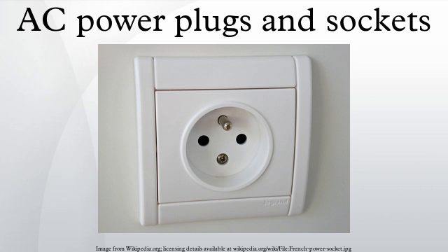Argentina: IRAM 2073 and 2071 and compatible types. The plug and socket used in Class A1 applications in Argentina is defined by IRAM. The applicable standards are IRAM 2073, 2-pole plugs with earthing contact for domestic and similar purposes, rated 10A and 20A, 250 VAC, and IRAM 2071, 2-pole socket outlets with earthing contact for 10A and 20A, 250 VAC, for fixed installations.